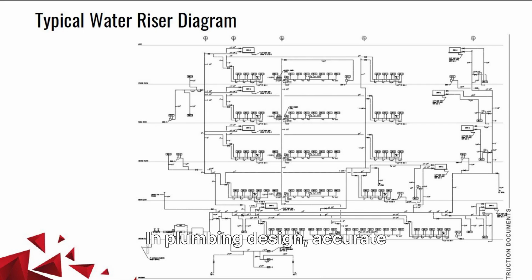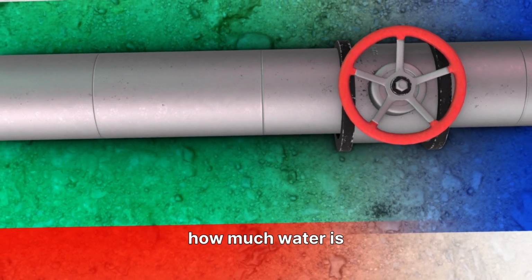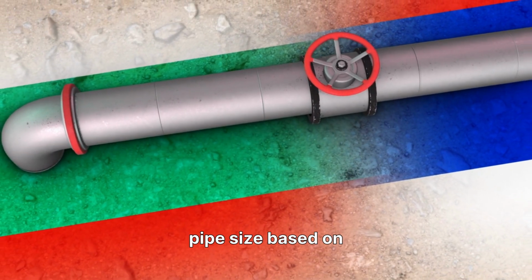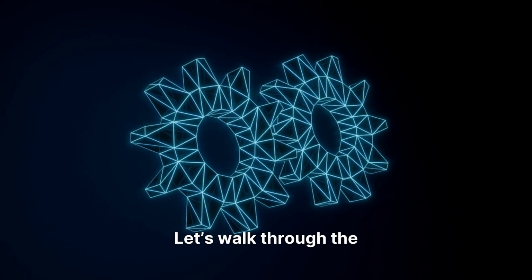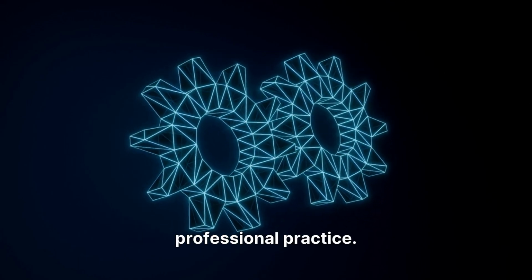In plumbing design, accurate domestic water pipe sizing is essential to ensure reliable water delivery, maintain pressure, and prevent excessive noise or energy loss. The process involves determining how much water is needed for both hot and cold systems, and then selecting the right pipe size based on friction loss and velocity criteria. Let's walk through the step-by-step procedure used by engineers and designers in professional practice.